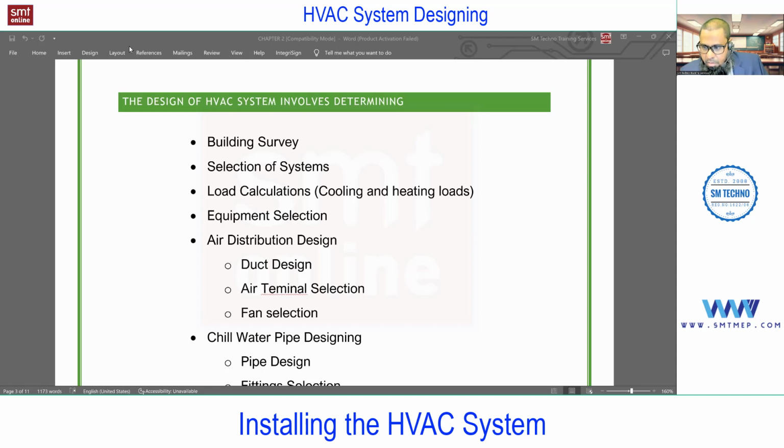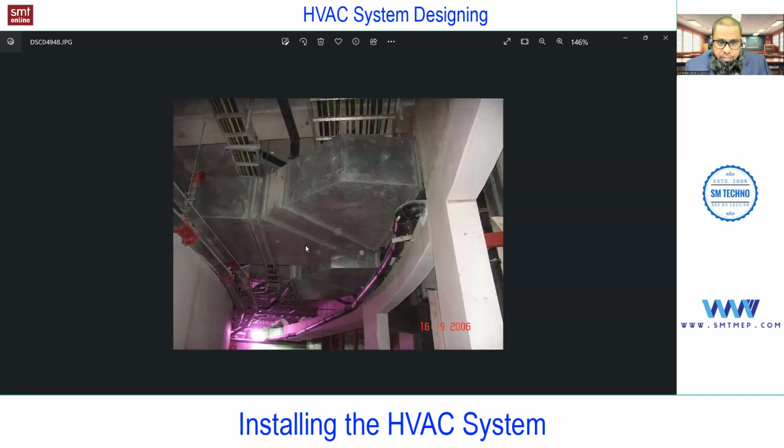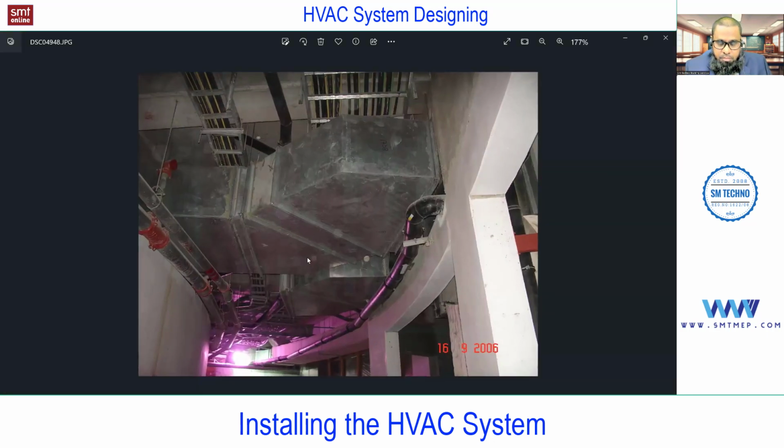That is when I'm working on the Revit. Okay, so you're working on the Revit. So forget about the Revit. So your question is why this cable tray is above this duct, right? Not only cable trays, that means how the levels are adjusted with the coordination point of view, so that it cannot clash with other services. This is a very, very important point. And in building survey chapter 6, we have point number 8 related to this. In detail we'll discuss. I'll give you a quick idea.